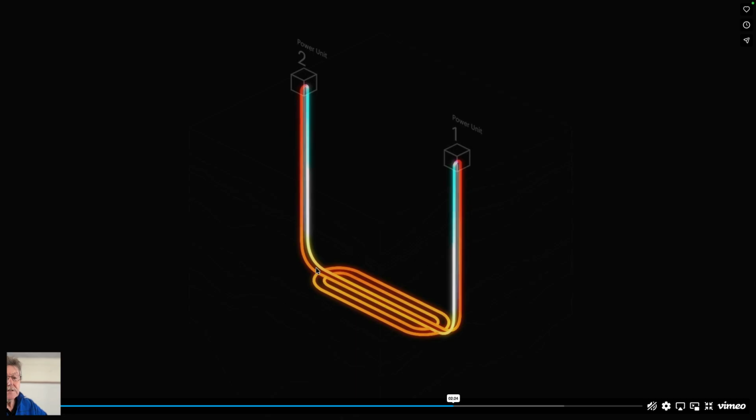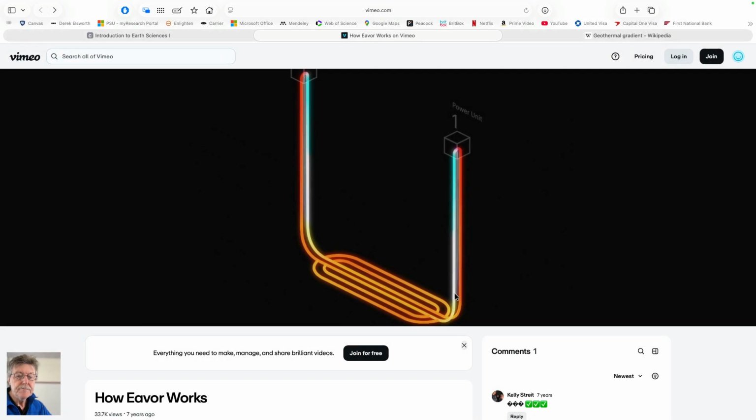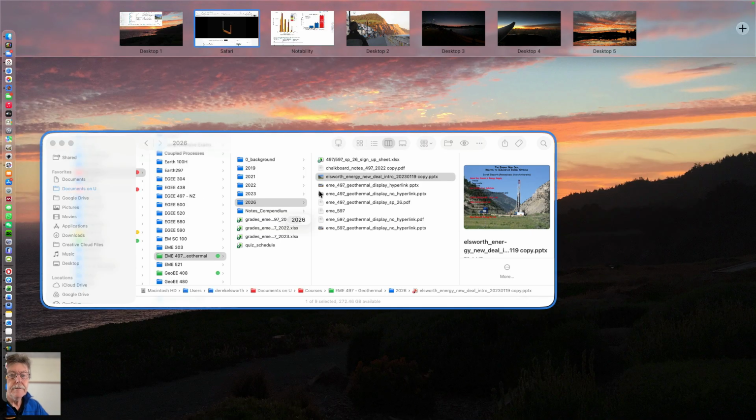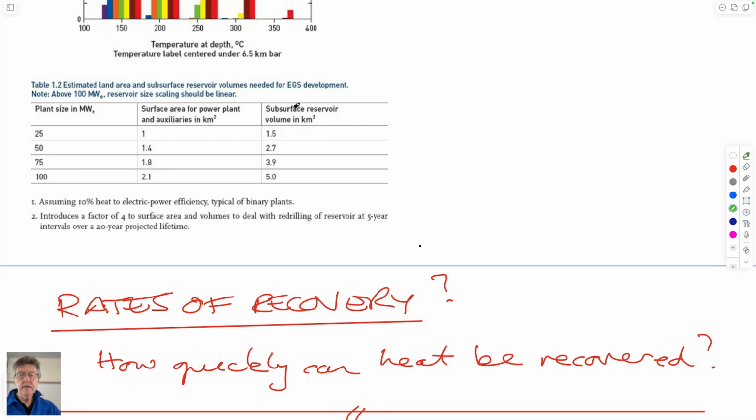It heats up as it goes across, so this is much less dense than it is on this side, and therefore it drives itself. So that circuit could survive without any so-called parasitic losses. You don't have to provide a pump in that particular case. But the problem with this is that if you think about the behavior within this, you have this is your circuit, it goes down, it goes across, and then it comes up